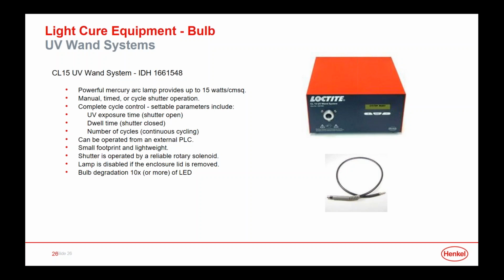It offers a lot of capability and flexibility for curing products that don't respond well to LED. It also offers a very high level of intensity. You can deliver as many as 15 watts per centimeter squared of intensity at the point of the light source. So this is a very common solution for us when recommending adhesive products when we can't use an LED solution.